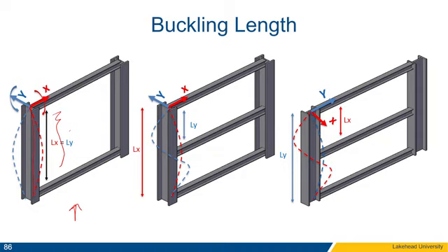One thing I would like to first remind you about is the naming of the axes. We agreed that usually axis X is the one perpendicular to the web, and axis Y is the one parallel to the web. And no matter how the column is rotated, those axes naming will still remain the same.